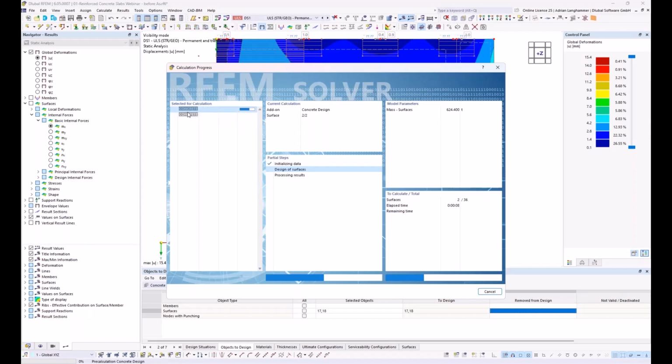I have now two concrete entries. The first calculation is the required reinforcement. So with changing the reinforcement, there could be also changes regarding the inner lever arm or the effective depth, depending on the defined reinforcement. And the second calculation is the automatic design of the existing reinforcement.